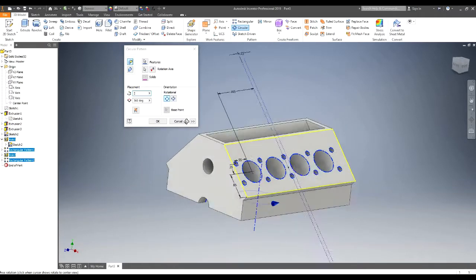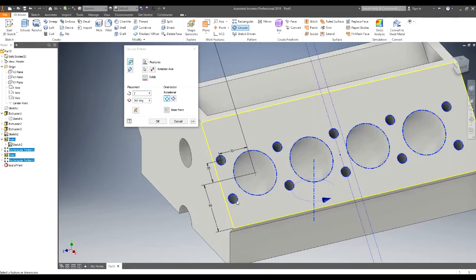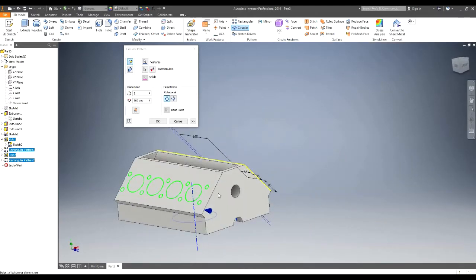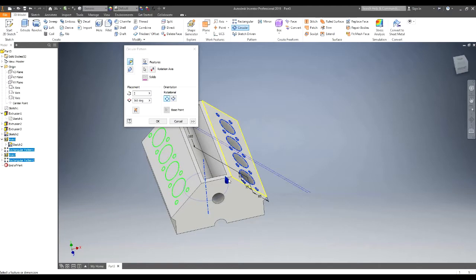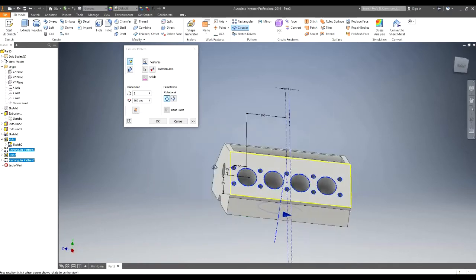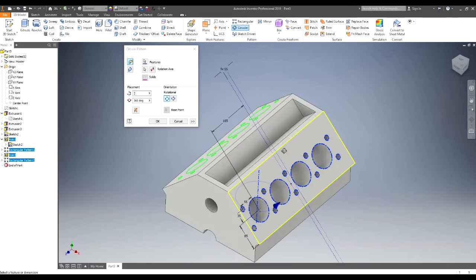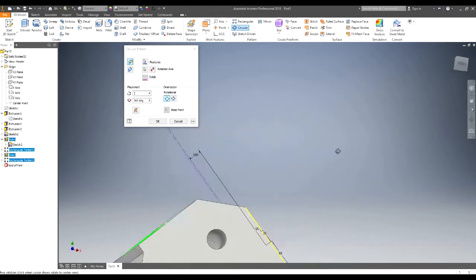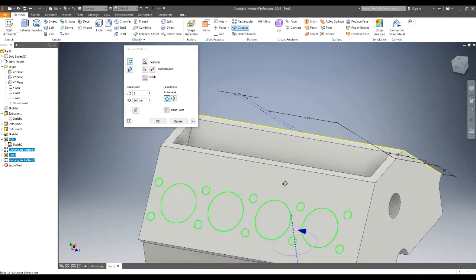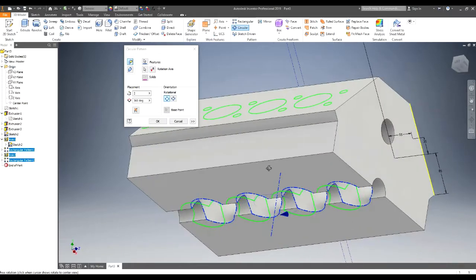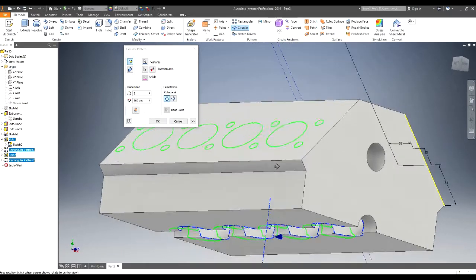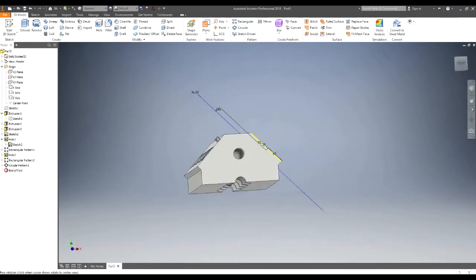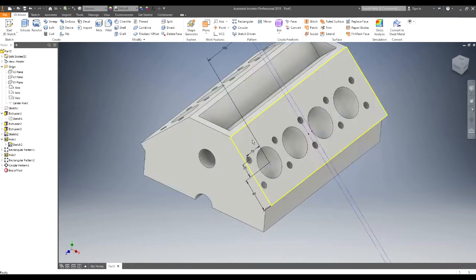And now you may be wondering, why are you not mirroring it? And it's simply because if we mirror this, the pistons, the 2 cylinders would be aligned, so the con rods will collide. So because all of these piston holes need an offset, by using a rotational pattern, the image would be the opposite on the other side. So that's exactly what we want. So I will now click on OK. So we're getting there.